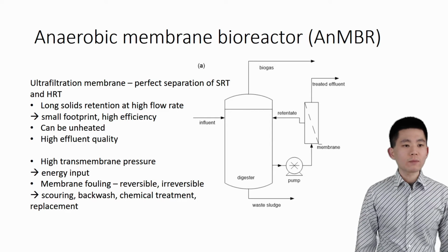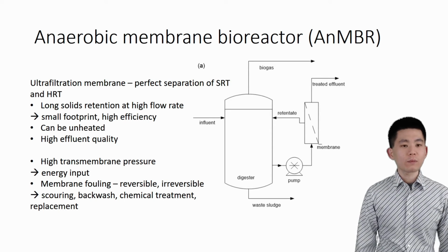Also note that the methane solubility increases as temperature decreases, so a lower proportion of methane is collected in the gas phase as more methane is wasted in effluent liquid when the digester is operating at a lower temperature.